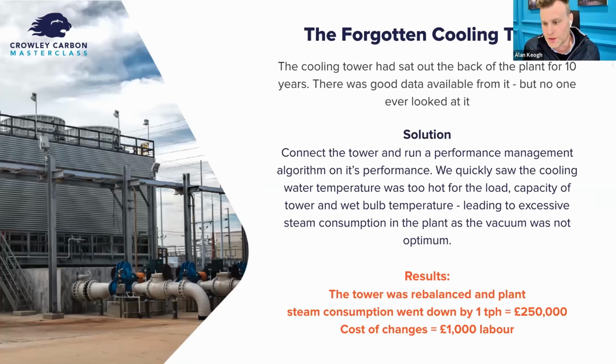This is a situation we worked on a year or so ago, where we were working in a plant and it had a very nice cooling tower with a very nice control system on it, but it was out the back. The PLC sat in the shed. Nobody ever looked at it. Lots of instrumentation potentially, but it wasn't connected to anything. And when we connected it up and ran it through our performance algorithms, we saw that the water coming out of the cooling tower was too hot for the load on the cooling tower and for the ambient conditions pertaining on the particular day.